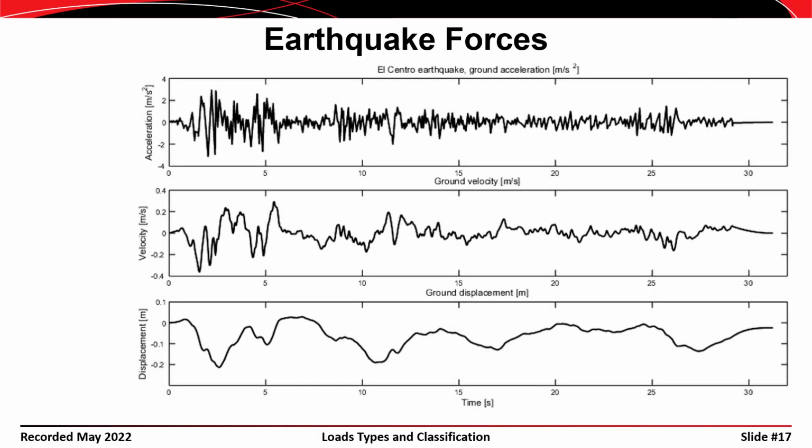Okay, let's shift our attention to earthquakes now, seismic forces. Seismic forces are a bit different than other forces, the way that the load is imposed. They're an inertial force as opposed to an externally acting force. They have their genesis in the idea that the ground moves under the building and then the building reacts to that motion. So this is a record of the El Centro earthquake.